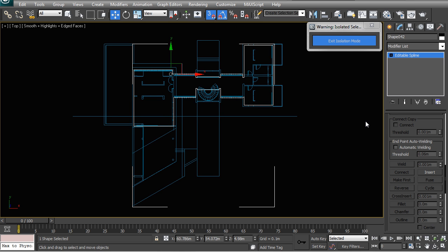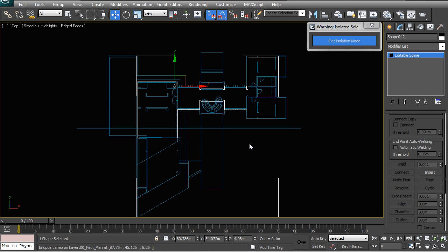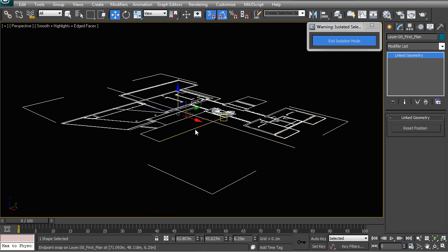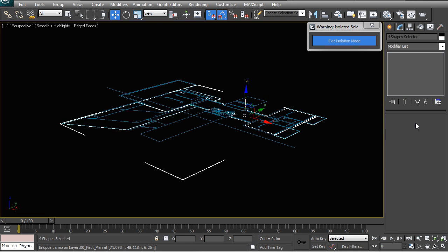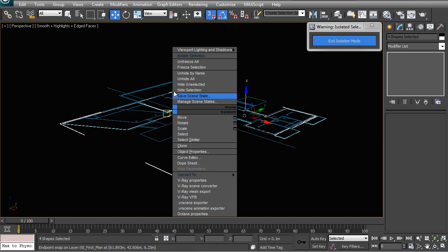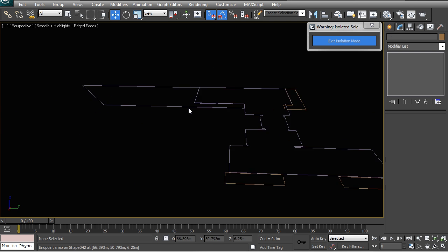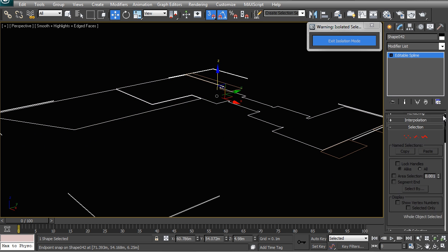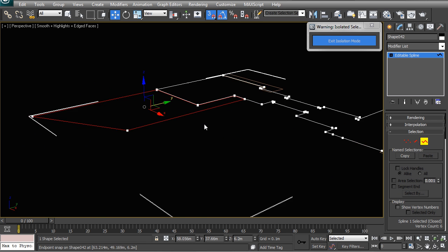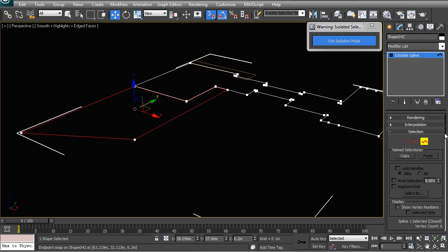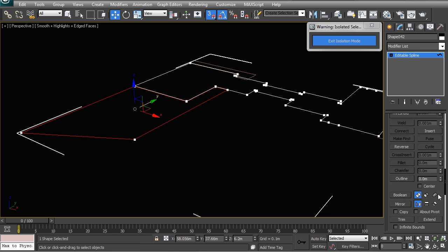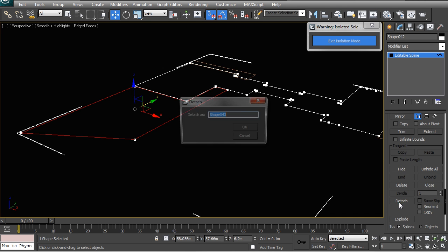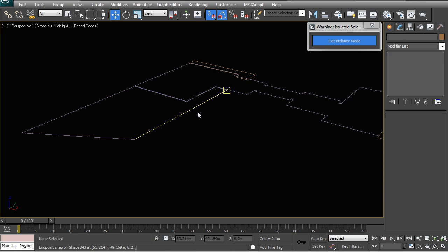So now that entire spline outline has been drawn, and if we have a look at it from 3D without this plan, we just Control-I that selection, you can isolate it, and this is basically what we've drawn so far. So the level that we have down here, we can even detach that if we want to. It may simplify things with our materials later, since you don't necessarily want to have the same material outside on the terrace as you do inside the building, especially in the bedrooms.